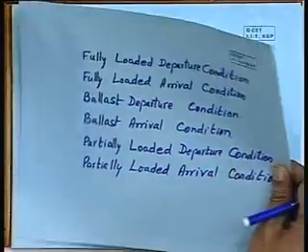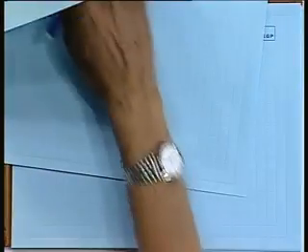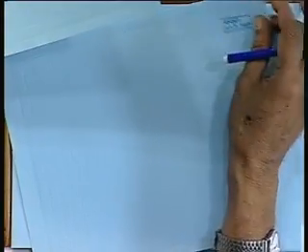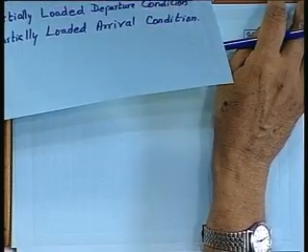Whatever the vessel is designed for, you take 60% of that as the load, and fill up the last two conditions with that. So one is a fully loaded condition, another is a fully empty condition, and the third one is a partly loaded condition. So we consider these six conditions as the ones which may induce the worst possible loading to the vessel during its entire life.